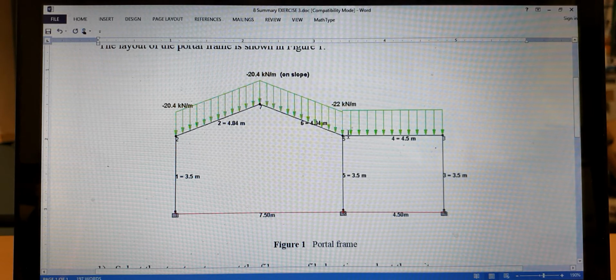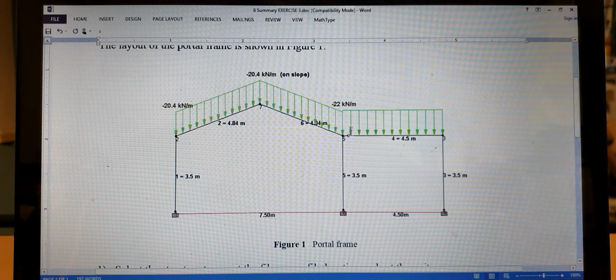So in order to release moment here, you need to introduce a hinge. So this is a symbol for hinge. Okay, so if you want to release the moment, in other words, you want to have a simple connection. For example, if you put this beam resting on a simple bracket to this column, meaning that you can introduce a hinge here. Okay, how to introduce hinge in STAAD.Pro?